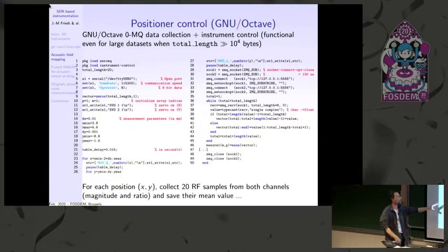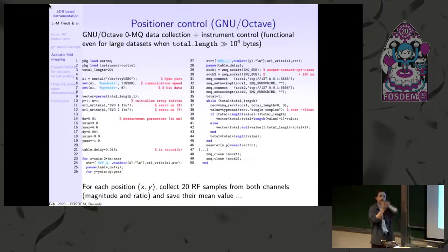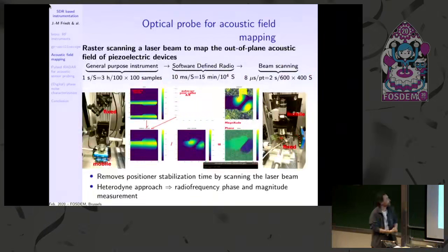And what's really important to me is I never stop the radio frequency stream, because with the B210, if I have 2 B210s, they start being synchronous, but you don't know what the phase offset is. So if at some point I stop the stream and I start it again, I start with a new phase offset, and I cannot compensate for it. So in this case, I keep on streaming radio frequency data, and at least if I calibrate my phase offset, I know it's the same throughout the data I collect. So this is the kind of experimental setup we have.